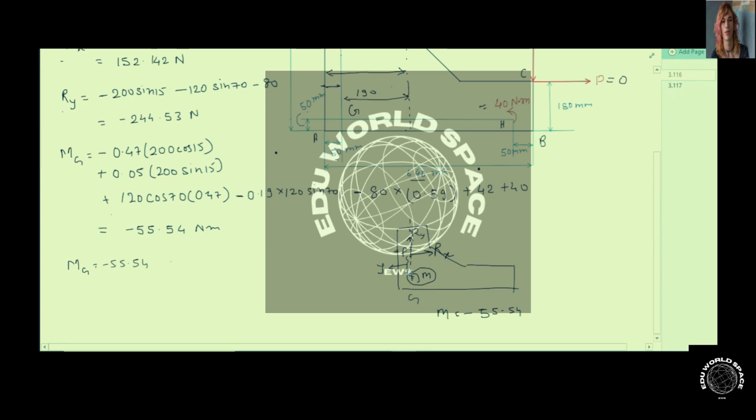Now after the shifting of the system, the moment due to the component Ry will be 0 because it will be passing through the point G. The only component will be due to Rx, and it will cause a clockwise couple, so it will be minus sign Rx multiplied by the vertical distance y. So the vertical distance can be calculated from this equation, since Rx is already known. So y comes out to be 0.227 meter. So this is the distance from point B on the line GF.